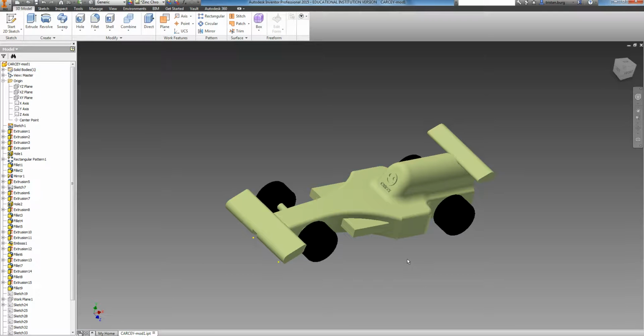But there's nothing stopping you modifying more than one thing. Like if you've been assigned by your group to modify the rear wing for your science project, you might try and see how the length or the width of that particular wing affects the flow and the drag of your car. But if you really want to get into this project, there's nothing stopping you doing 5 modifications of the length of the wing, 5 modifications of the width, 5 modifications of the height or the angle, all sorts of things till you find the optimum rear wing design for your car. You can incorporate that into your science report to make it a bit more detailed, or you can just do it as part of your own team's work, to make your car the best car possible.